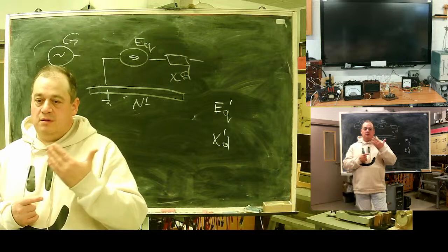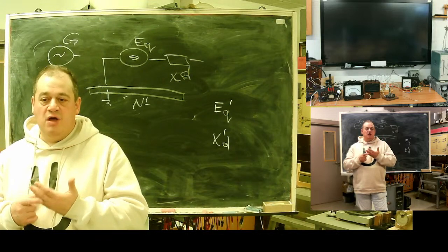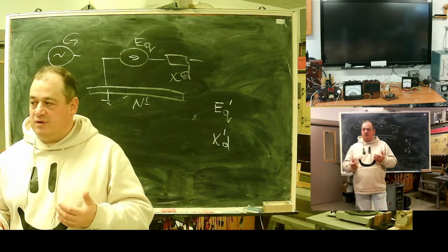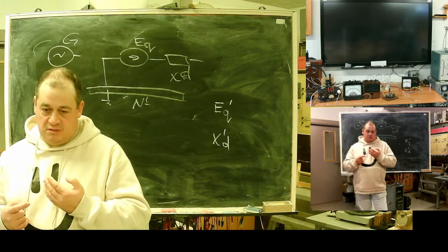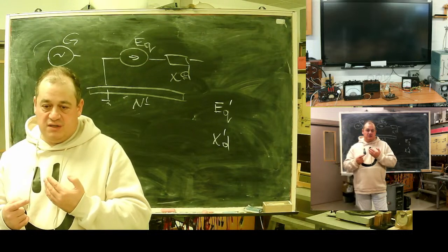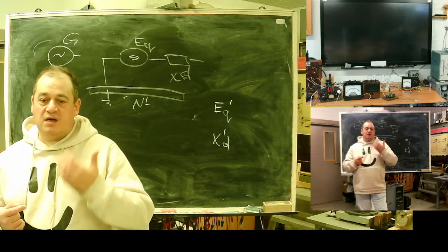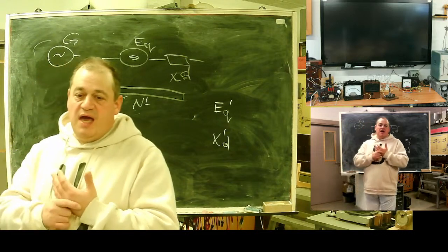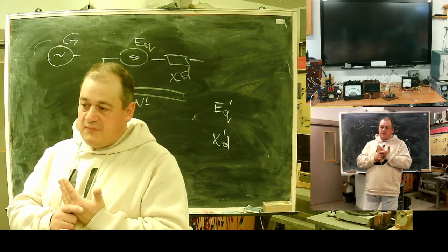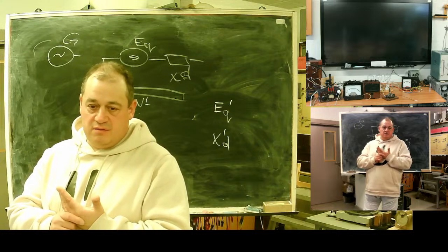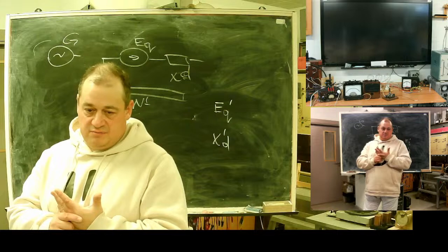When oscillations begin at a very early stage, maybe because of irregularities in water flow, current will be induced in this ring, and the magnetic field of this ring will brake the rotor. It will act as a damper.